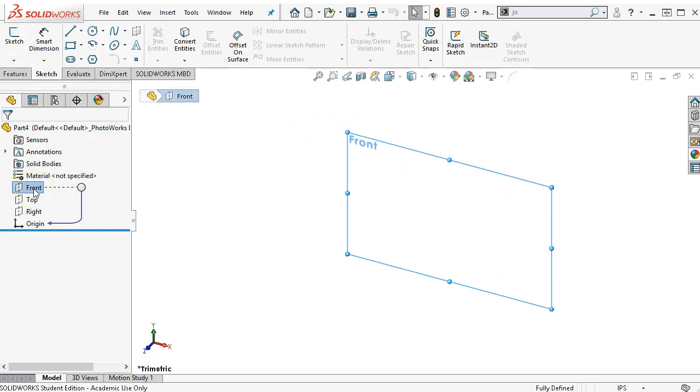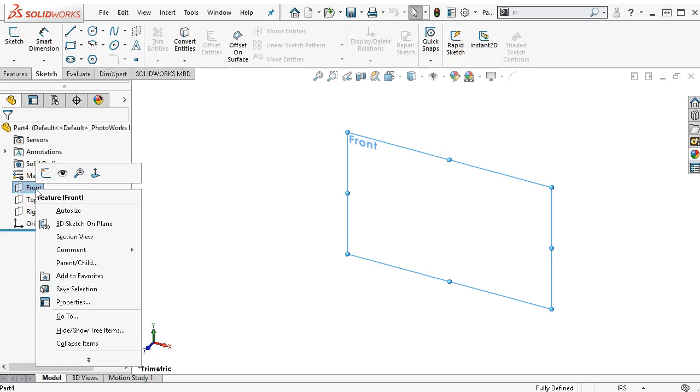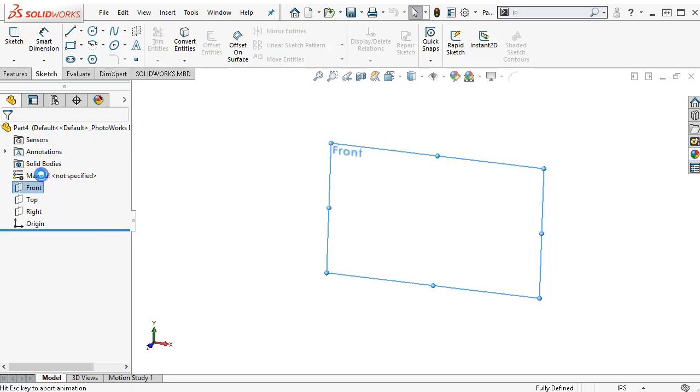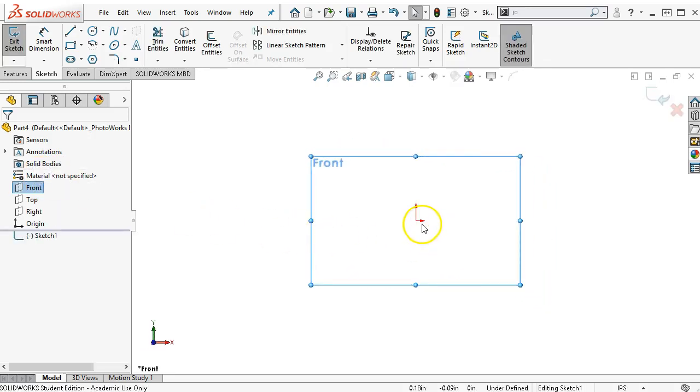Pre-selecting, I like pre-selecting. If you've watched any of the other videos, I pre-select a lot. So if you have the item staged, ready to go, then whatever function you're telling it to do is usually a little bit quicker. And then we talked about the front plane, and then right-clicking, and then we'll go into the sketch. So I have these icons across the top, and we can open the sketch.